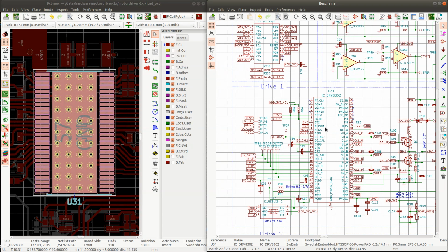I think that the most reasonable approach is actually that I'll configure the timers for generating the PWM, and start from there, make sure that this chip works, make sure that I'm getting some waveforms on the MOSFETs, and then while I'm doing this, I can also keep in the back of my head how I'm going to implement the code for all the other things that relate closely to the motor control task.